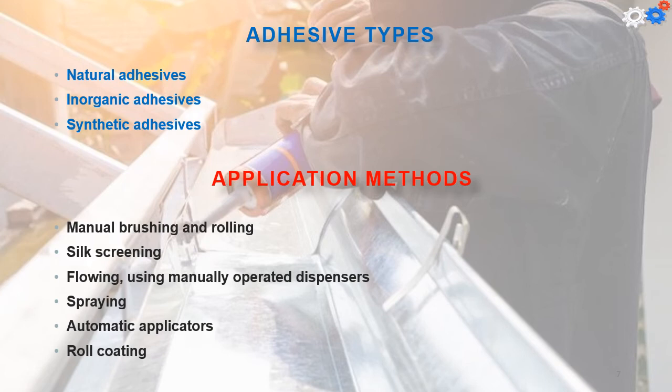The application methods for adhesives are manual brushing and rolling, silk screening, flowing using manually operated dispensers, spraying, automatic applicators, or roll coating.